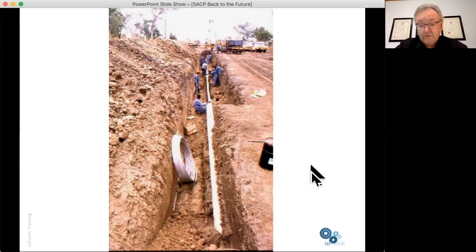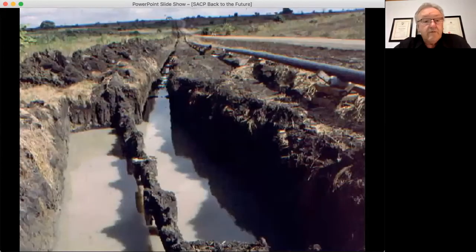Now, this was so effective that in an area of the pipeline, and here you can see a photograph of the old pipeline and a replacement pipeline over here on the right-hand side, the magnesium ribbon was installed to provide temporary protection in an area intended to be about 5 years. And something like 10 years later, when the system was upgraded, the ribbon was found to be still operational.